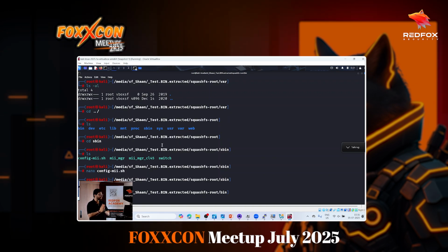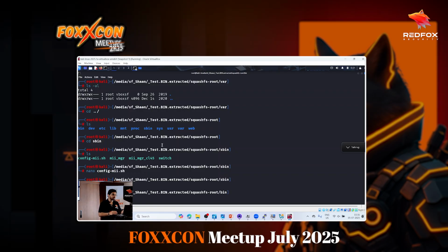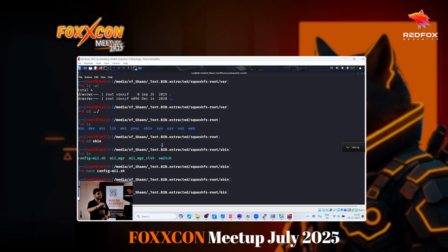Baud rate is quite easy to understand. You just try multiple things and it will just work out. In fact, the logic analyzer software has a brute force functionality that you can use. It will brute force through a few of them, and then it will tell you which one it could be.